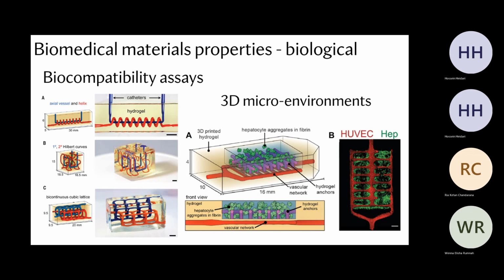I can control the exposure time, look, not below a threshold because then it will just not form anything. But beyond that threshold where you have the object, you can increase the exposure time to increase the stiffness. So you can basically modulate stiffness at various layers. And moreover, you can actually change the intensity of light across that state. The screen that you saw on those printers can do various intensities, just like this screen. You can have brighter spots and darker spots, but it doesn't utilize that. If it did, then different pixels across the area would see different amounts of energy. And that way you can get different amounts of cross-linking and conversion and therefore stiffnesses.